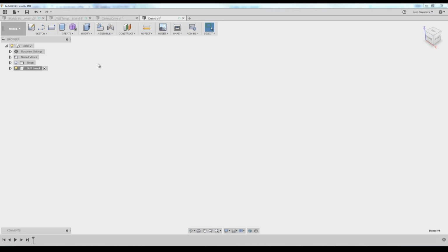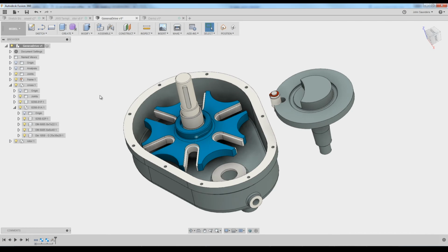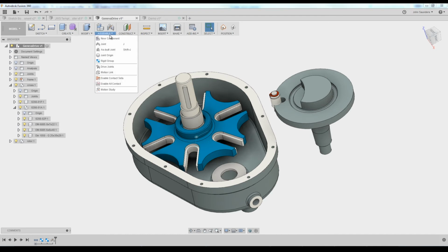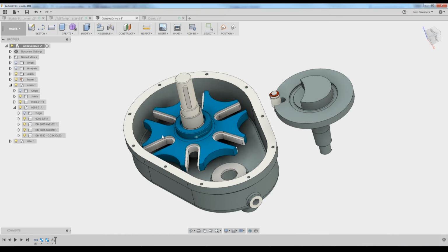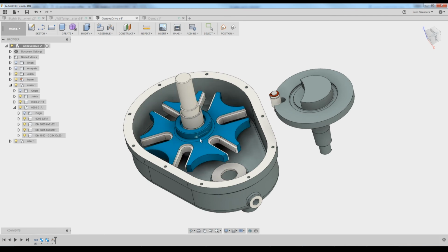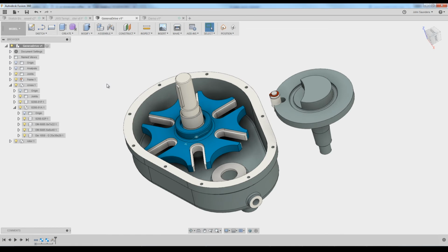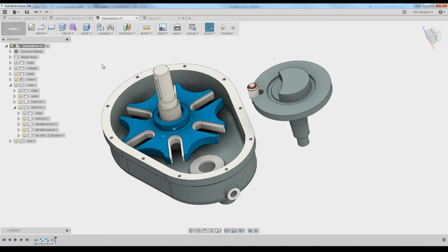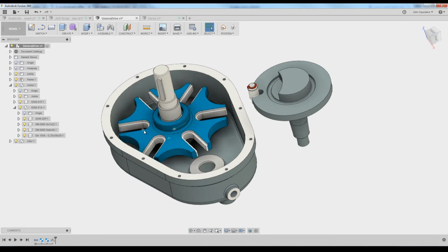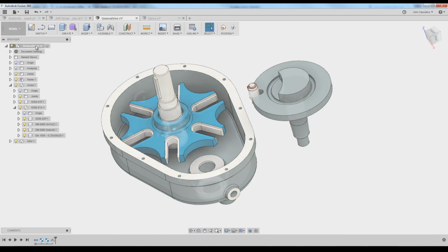So again, why does this matter? It matters mostly because when you go to create CAD files, oftentimes you're going to want to either machine those via CAM, or you're going to want to create joints under Assemble. Joints are what let you have things rotate and move relative to each other. You can only create joints between components. What's cool about Fusion 360, but different than other CAD software, is that all of these individual components are within this single file.